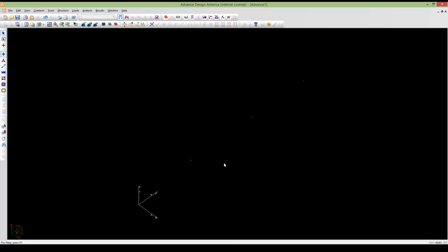Okay, so if you check the nodes here, they are already defined here. As you see, I have 3 spans, and I have some small beam elements that will be cast by slab. So for the first stages, I will have the beams here, pretension beams, and after that, with pouring of the concrete, the extra small beam elements will be activated here between these nodes.